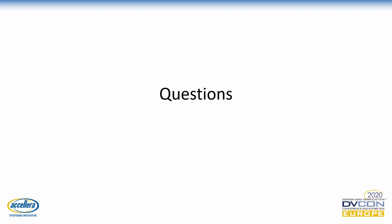Your main scope here was, sorry, for the methods themselves, I'm talking about the two different formal methods to do the verification. You can definitely use different vendors to do probably the similar thing. But for Questa, we are using the Questa side of the tools. The compiler I'm using for generating the table is the Questa tool. Vlog is the common compiler across the Questa tools. Questa simulation also uses Vlog to compile the RTL, and then the formal stuff. So the results are from the Questa tool.